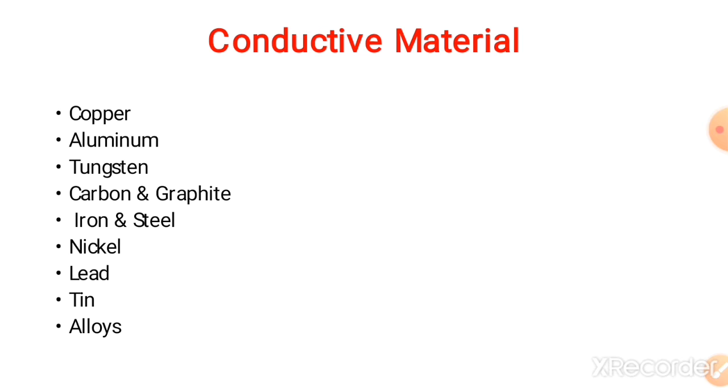Tungsten has great hardness, high boiling point and high melting point, coupled with its resistance to abrasion. Resistance to abrasion means resistance to wear, and it is also called scratch resistance. The typical operating conditions of tungsten material: the voltage AC or DC up to 230 volt, the current up to 15 ampere. The typical applications of tungsten contacts are in battery ignition systems, vibrators and electrical razors.